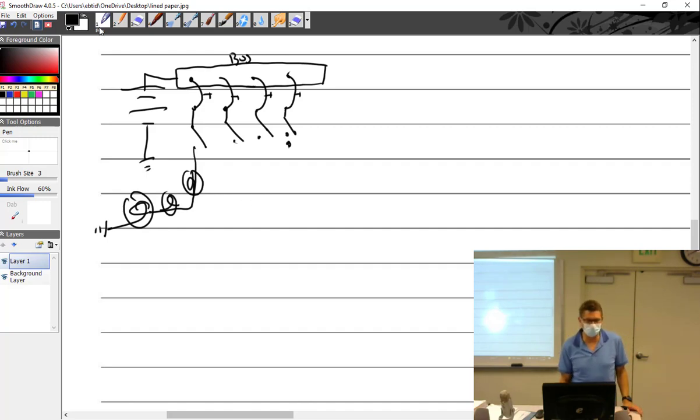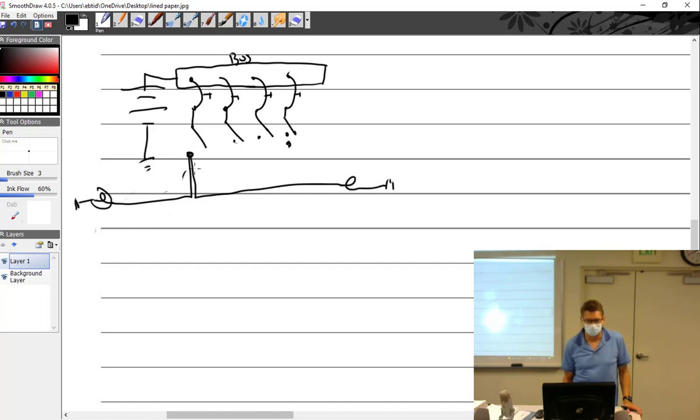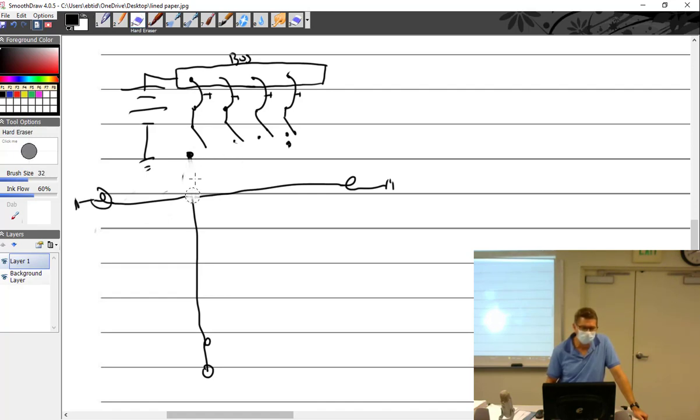So the way it would be done, if this is my nav light switch right here, I want the nav lights on, it's going to go out this way to this light, and then it's going to parallel out to this light. Another one going out here to this light. So you can see they're all parallel to each other. They're all tied into this one spot, but they are not in series with each other. They're all in parallel. It just doesn't look like it because maybe I could have drawn it a little bit better to make that point better.